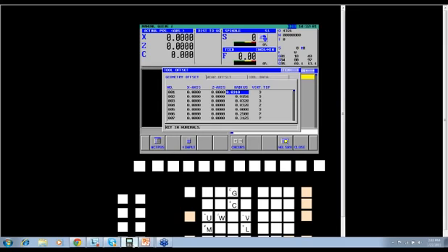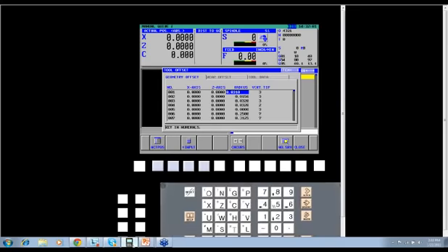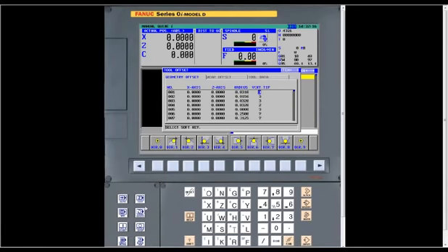All right, the next one's very important also, the virtual tip, because what that's used for is the orientation of the tool. The ones you're going to use the most: a number 3 is typically going to be an OD turning tool. A number 2 will be an ID boring bar. A number 7 will be a drill. Those are going to be the 3 that you use the most. That's what you see on this first page, tools 1 through 7. We have a 3, 3, 3, 2, a 3, and then 2, 7. So typically with that, that's what you want there.